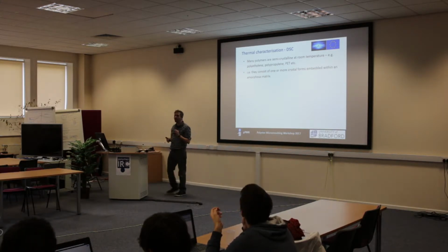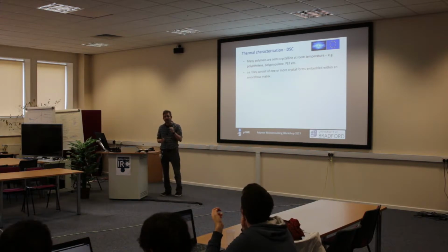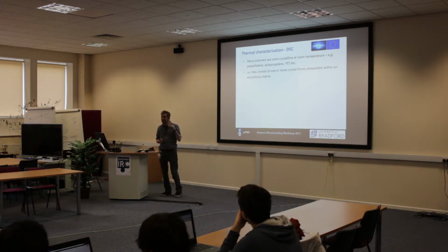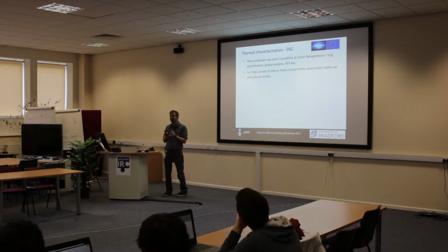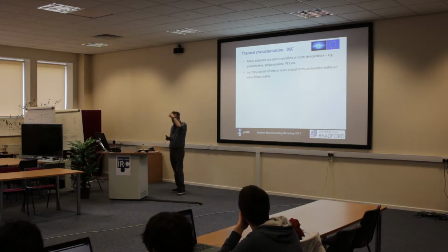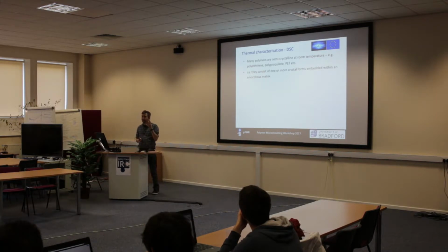Crystals can take more than one form, okay? So a crystal of water, for instance, in ice form, can have quite a lot of different crystal forms depending on what's happened to it prior to it forming, okay? And polymers are the same. They exhibit what's called polymorphism, okay? So a material I'm using next door, PVDF, it's a semi-crystalline material, that has 4 different crystal forms depending on how you form it, okay? So you end up with these polymorphs.